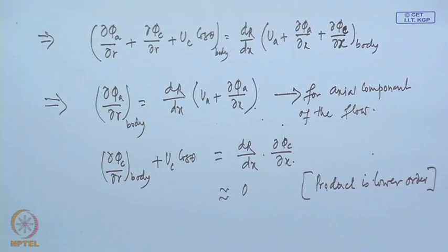So, looking to what we have done today, first of all we approximated or simplified the expression for the source distribution when the cone is very slender, from the more accurate general solution that we obtained in the last class. Further then we went on to see the asymmetric flow, when the flow is non-axisymmetric with respect to the body, that is the flow is at an angle of attack.